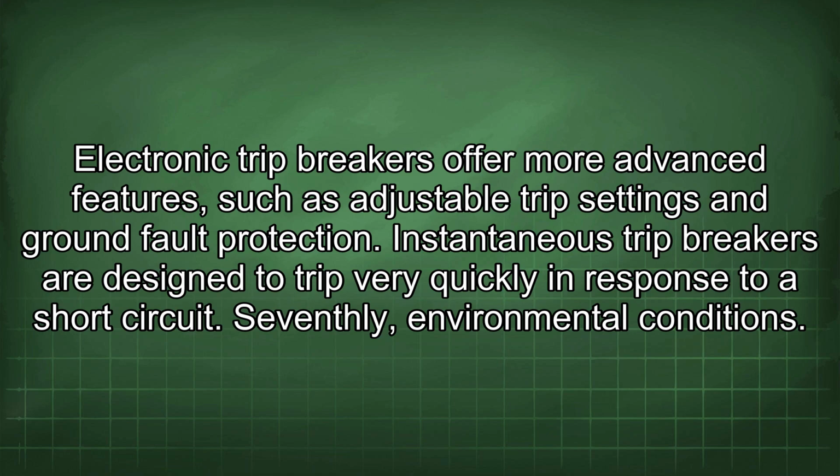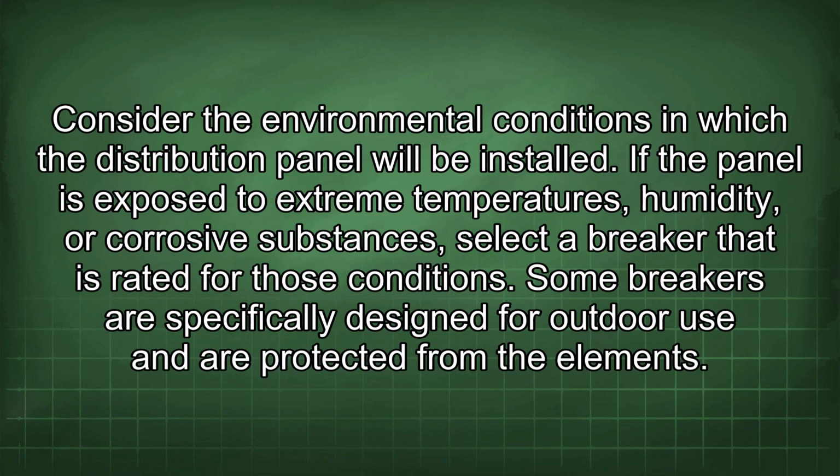Seventhly, environmental conditions. Consider the environmental conditions in which the distribution panel will be installed. If the panel is exposed to extreme temperatures, humidity, or corrosive substances, select a breaker that is rated for those conditions. Some breakers are specifically designed for outdoor use and are protected from the elements.